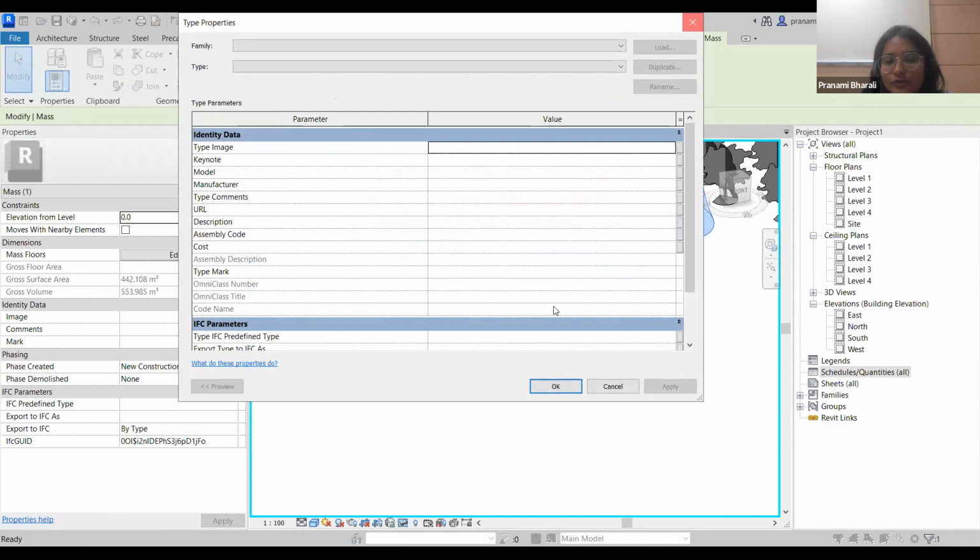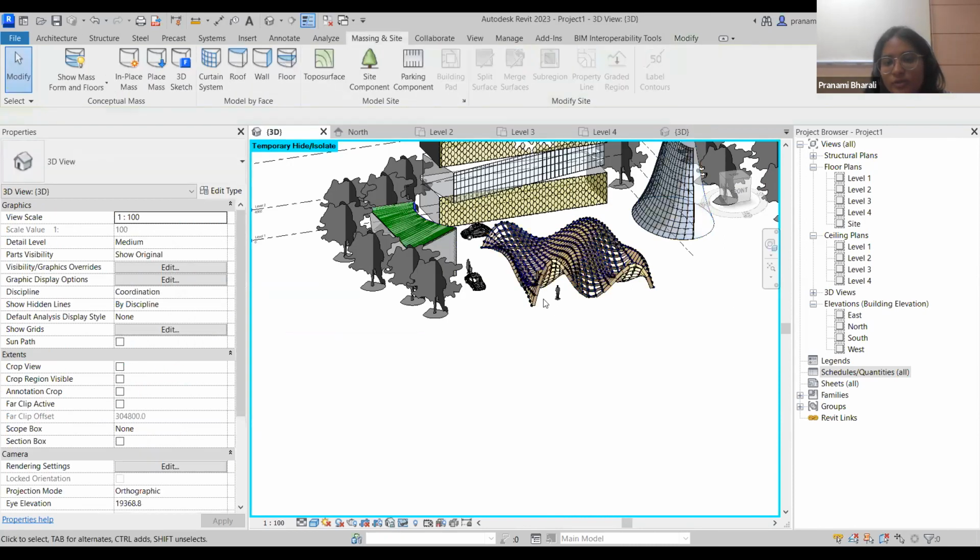But for placing the thickness, whenever I place those point elements, make sure you are placing those point elements at an offset, maybe on the downward or the upward side. Make sure to place more point elements accordingly, and you have to select every point element and make a roof. Make a form accordingly. So you can try it out accordingly.